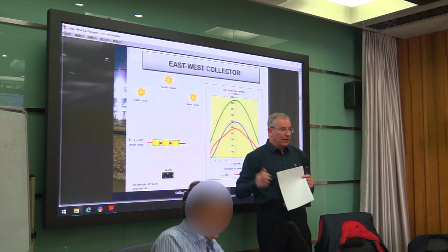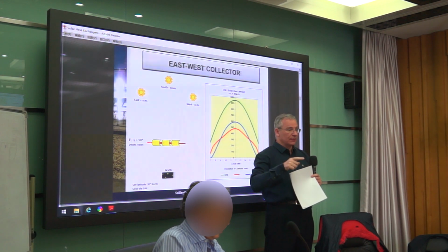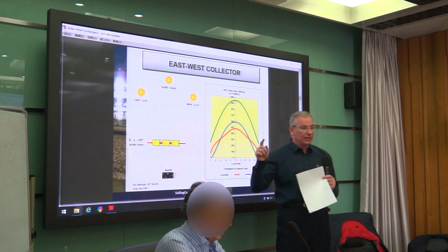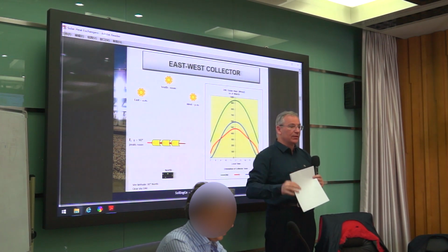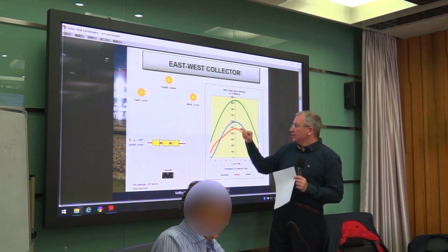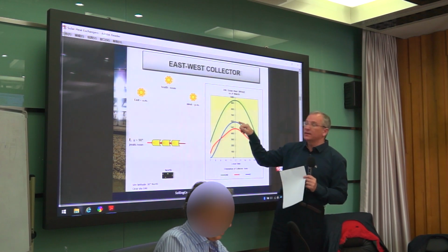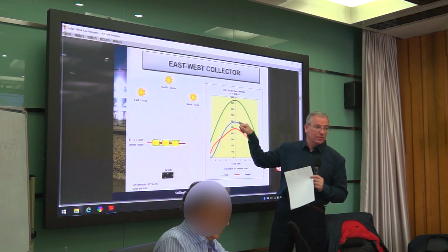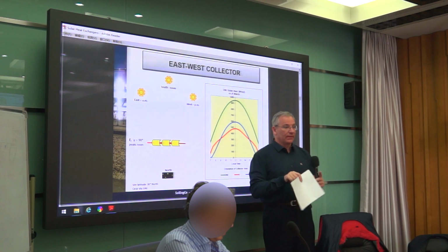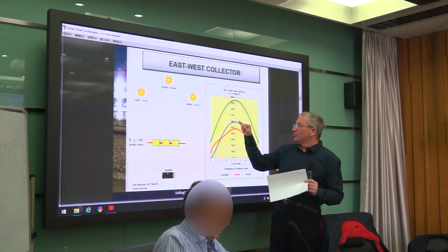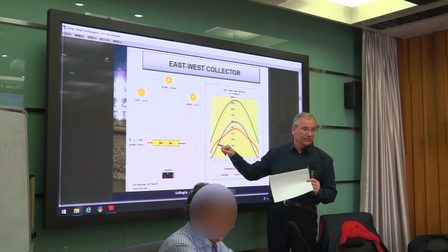Please be aware that we still have a solar multiple of 1. Mrs. Lee said it perfectly: with a solar multiple of 1, all the energy coming from the solar field will be utilized at the steam turbine. So if we can accommodate all the energy coming here in the power block, we will definitely get much more power. In other words, if we design the steam turbine from this point, then this orientation will definitely bring higher output at noon, but no output here and less output here. It's clear.